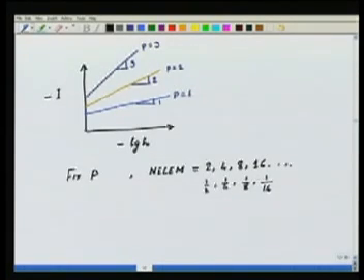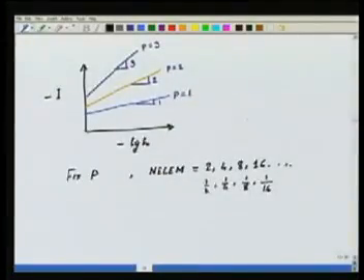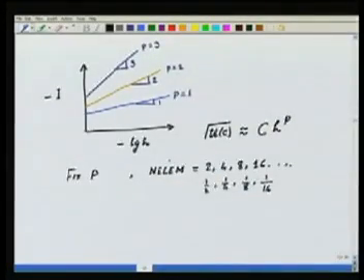For these values I should get curves like this. So, if you can get this, again it is a good proof that your program is doing what it should be doing. That is, we are seeing a ch to the power of p rate of convergence in the square root of the strain energy of the error, which we had talked about earlier. That is, with the h, that is, as the mesh is refined, I get the strain energy of the error, square root of that converges as ch to the power of p. This quantity is called the energy norm.